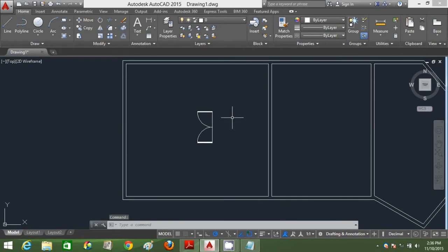Alright, so we got our doors already set. So now we're going to move it to the midpoint of this wall. So wait until the object snap appears and click on it. So I'm just going to set the boundary of that door. Select those two lines first before trimming it out. Type TR and enter twice and trim out the unwanted portions.